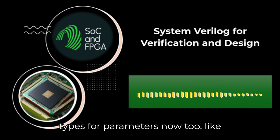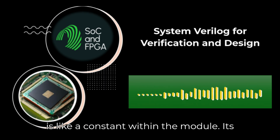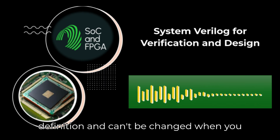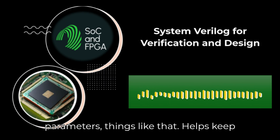You can specify types for parameters now, too, like parameter int WIDTH = 32. And localparam? What's that? Localparam is like a constant within the module. Its value is fixed within the module definition and can't be changed when you instantiate it. It's great for internal constants, derived values based on parameters, things like that.